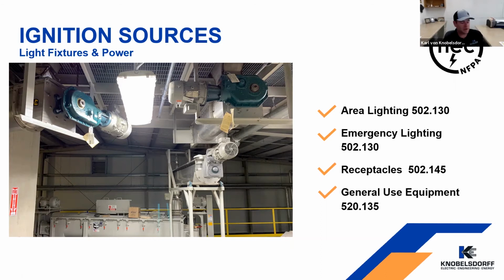Yeah, that one in our experience is definitely based on motor manufacturer, and each motor manufacturer, even by frame size, sometimes that changes by the different frame size for that manufacturer. So I know we deal a lot with Siemens and Baldor motors. Usually your motor rep can get you that information, but if they can't give you that T code information, you can't use that TEFC motor.